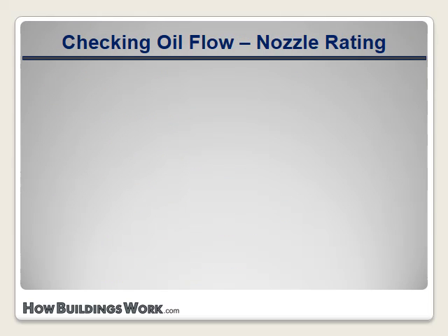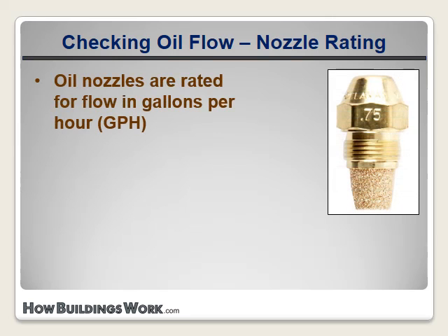We'll start by exploring the problem of excess fuel flow a little deeper. For oil-fired appliances, this is usually caused by an improperly sized nozzle. Nozzles are replaced as a matter of routine maintenance in oil appliances. They can be purchased in a wide variety of flow rates, since appliances with higher heat output require a greater oil flow rate. In fact, it's possible to calculate the proper size of the nozzle.